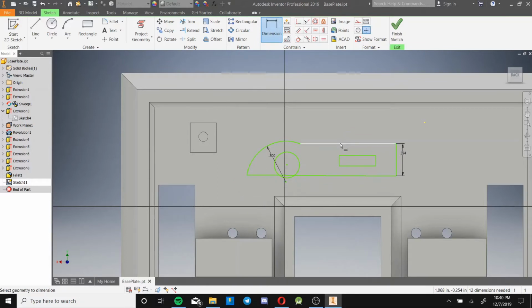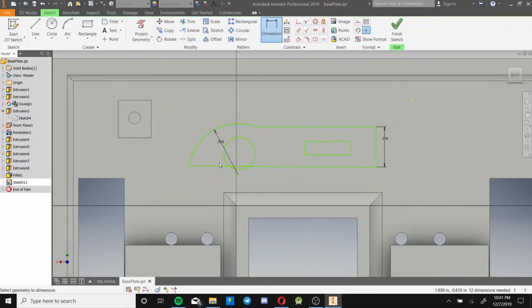You can define the length of lines. You can go from point to point and do it that way, or point to line segment, and you could do it that way. That's how you create dimensions. If you want to see how this line is slightly angled? You can't really tell, but it is slightly angled. If I go here and go down, I could do a horizontal dimension, or if I go to the side, I can specify the rise over the run, okay, the vertical dimension.